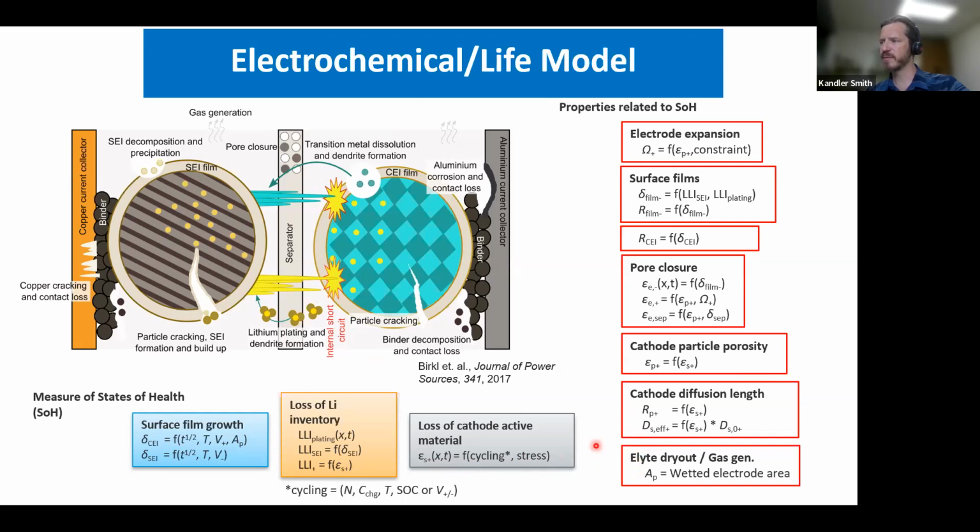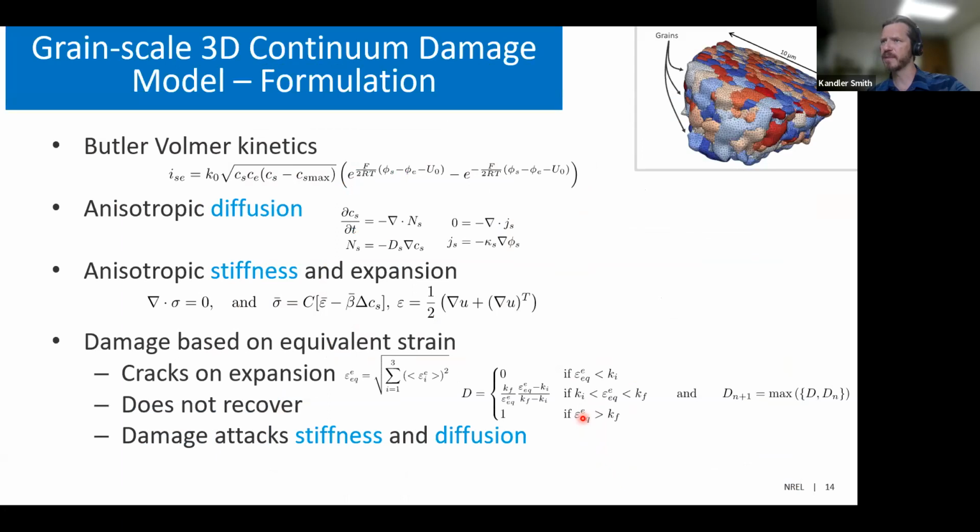So it's quite a lot of parameters to identify, and this is still a major challenge. Generally when you read literature on physics-based aging models, people assume maybe 3 parameters are changing or 5 parameters, but really there could be quite a bit more. And we still need good methods for novel diagnostics that can drill down and identify precisely which parameters are the ones that are changing. So those are some things that we're working on actively right now.